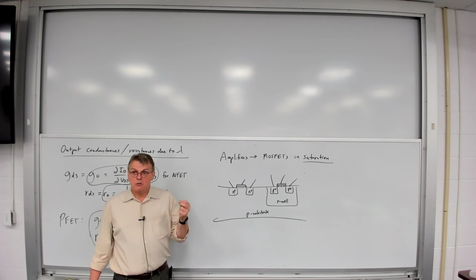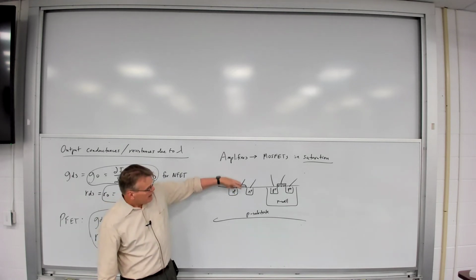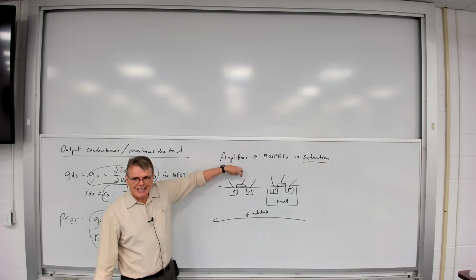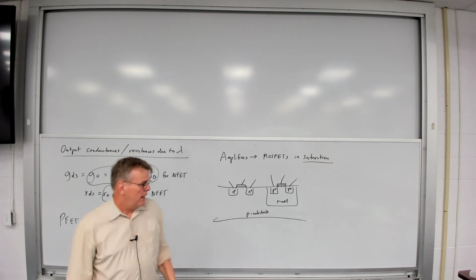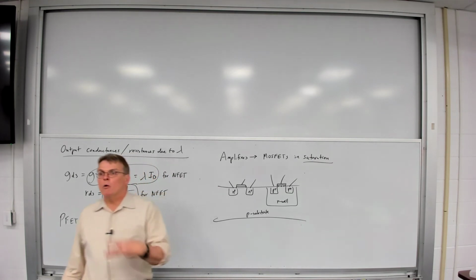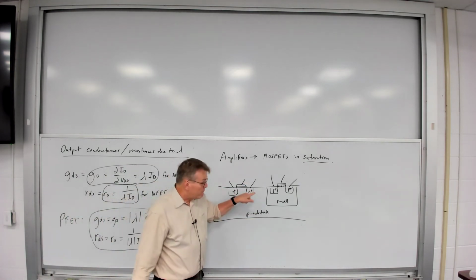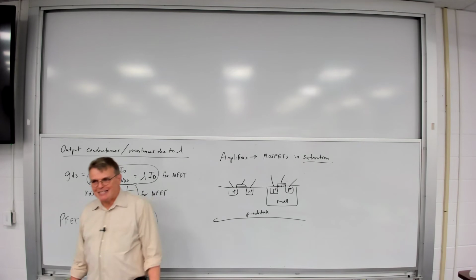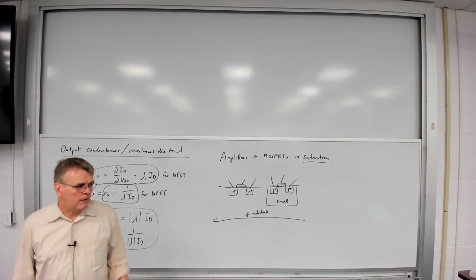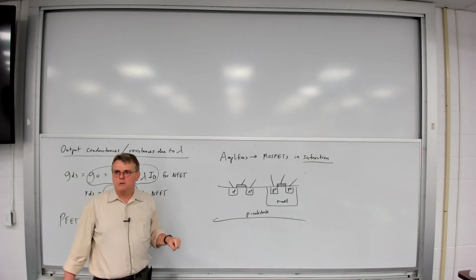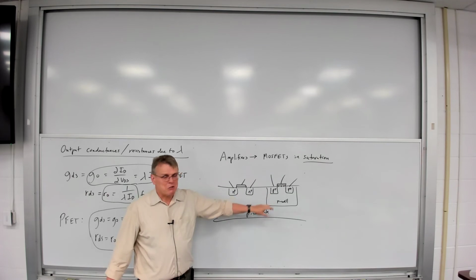In some of the newest transistors we have nowadays, we're building what are called FinFETs, where we're literally building the transistor with the channel and the gate above the surface. So we're actually building them as three-dimensional structures. And you will see dual and triple well processes. So actual cross-sections are far more sophisticated than this very simplistic image I drew for you. I'm doing this just because it gives you the picture. But when you start looking at modern processes, you'll find things are much more sophisticated than just this alone.